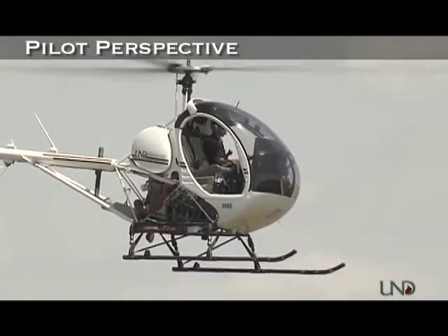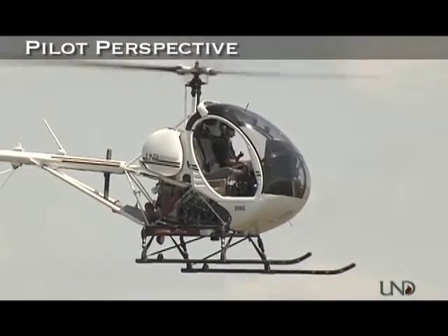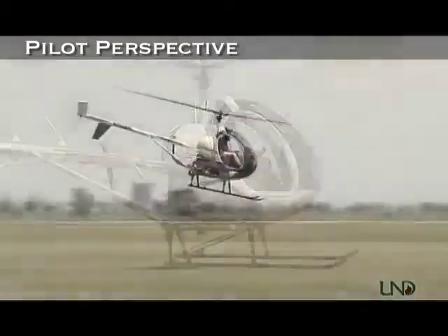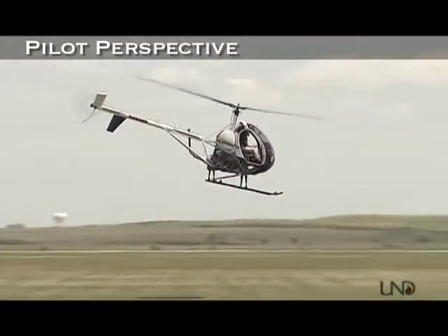It's basically the point where the helicopter moves from hovering in its own downwash to clean air, and basically we get all kinds of aerodynamic benefits from operating above ETL. It gives us less fuel burn, higher efficiency of the rotors, and generally overall we use less power.